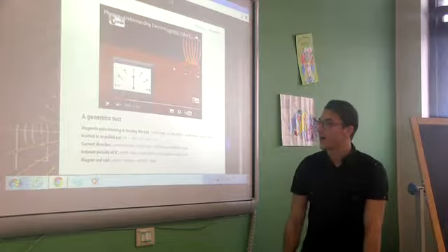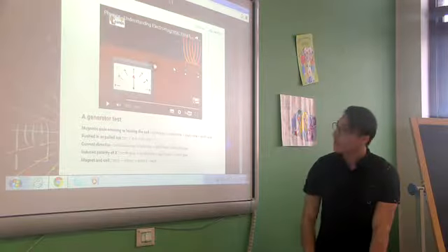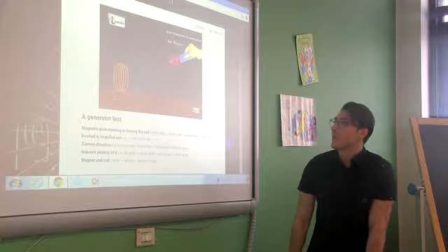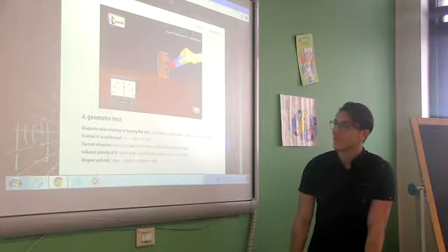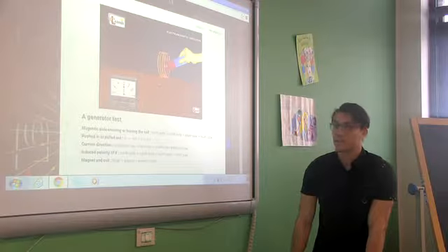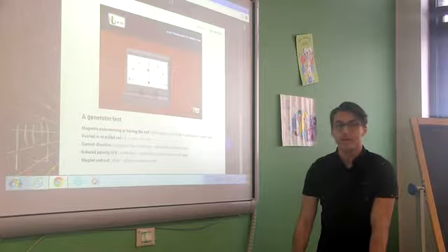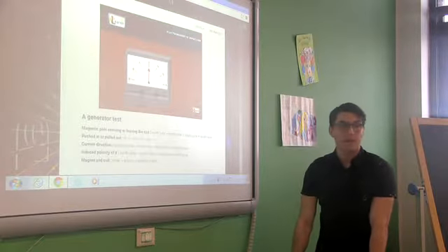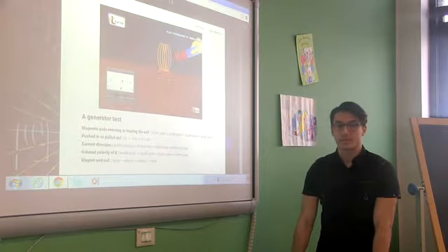Now I show you a coil of insulated wire connected to a galvanometer. When one end of a bar magnet is pushed into the coil, the galvanometer deflects. This is because the movement of a bar magnet causes an induced EMF in the coil. The induced PD causes a current because the coil is part of a complete circuit.